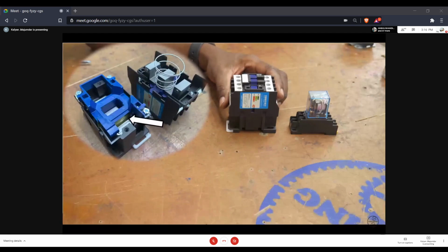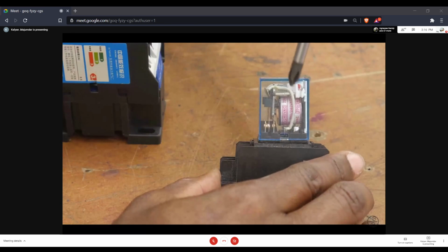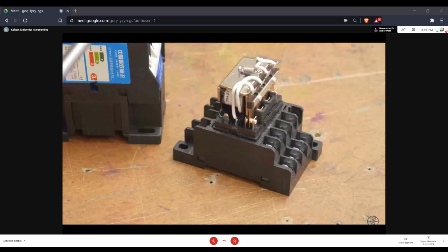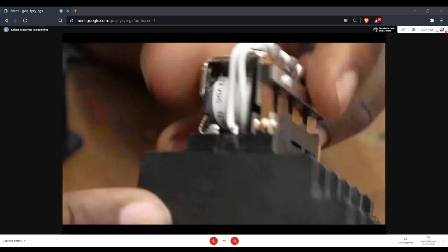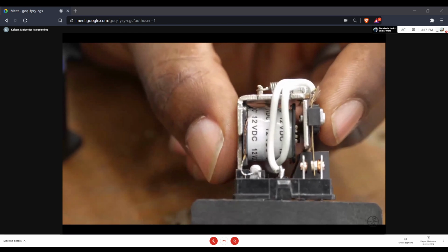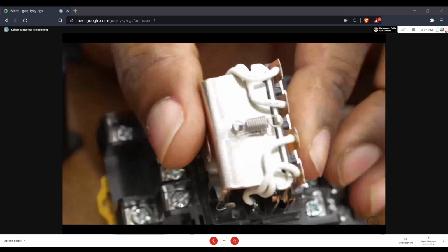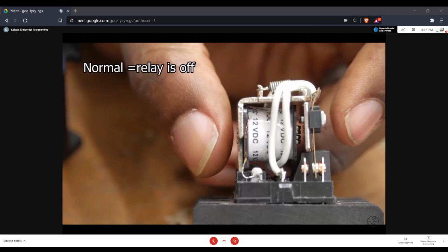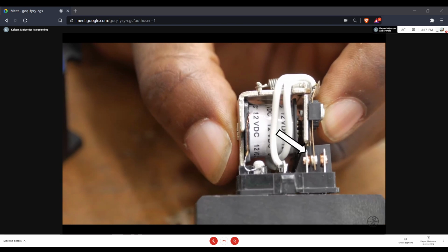Inside of this box is a coil that is identical to the coil I showed you earlier. Taking a closer look, you can see that this relay also has a coil right here. All right, let's switch to a larger one so that it's easier to see the wires in the coil. Here you can see 4 tabs which are connected to a lever. The lever is actuated by the magnet as well as this spring that's on top. The relay has 2 positions. We have what's called the normal position, which is the one you're looking at now, and then we have the activated position, which is what it looks like when the coil is turned on.